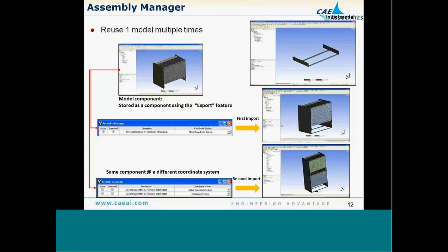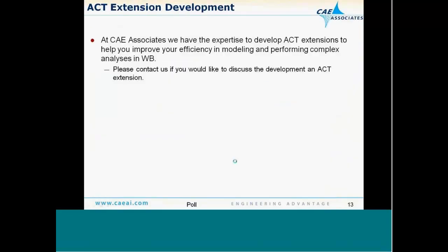And then you can choose to import that Mechanical simulation into your existing project in here. So all the mesh, contacts, material properties, loads, everything that used to be in this standalone simulation is now added to the existing project. And then you could also add some other, maybe it's the same component and you just put it in a different location, whatever the case is. So this is combining different Mechanical databases all in one. So that's a nice, very powerful one. But again, that was something that was developed by ANSYS for a particular customer.